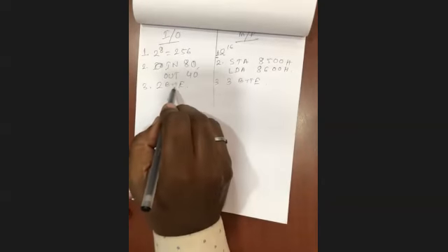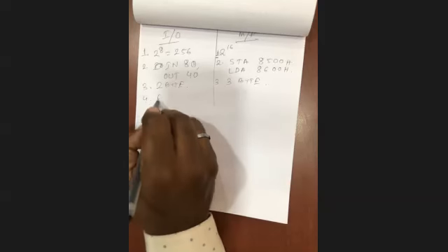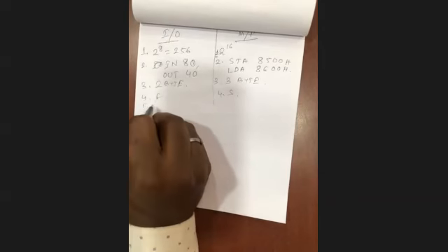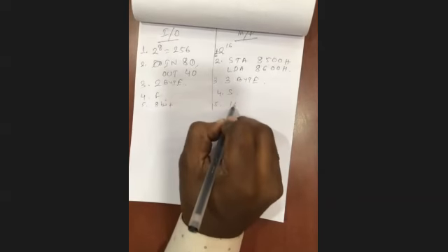Next, if the bytes are more, then more machine cycles are needed, so the time also will be more. Over here it is faster, and it's slower over there. Number 5: address bus 8-bit wide, address bus 16-bit wide. That is the whole difference of IO mapped IO and memory mapped IO.